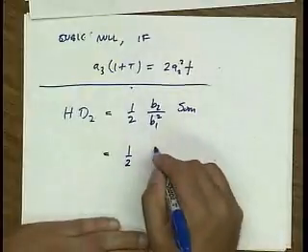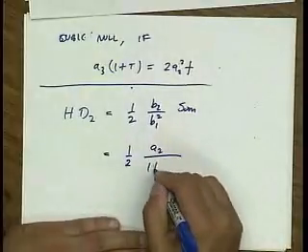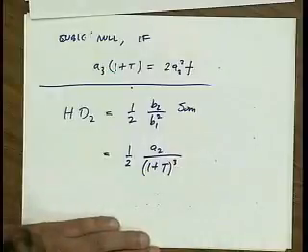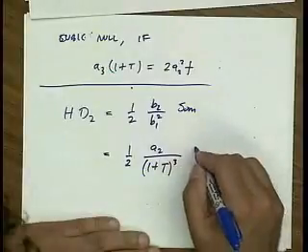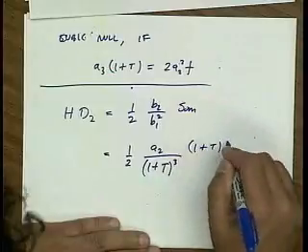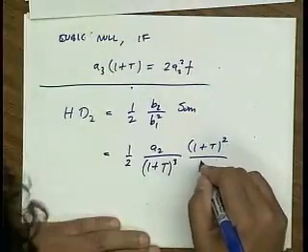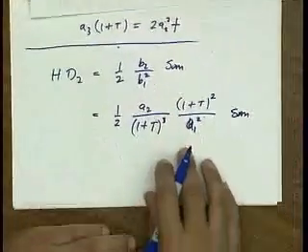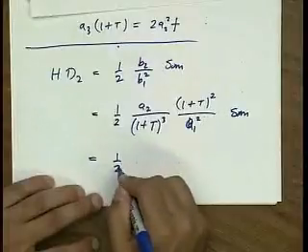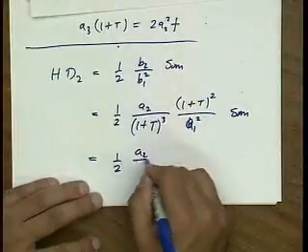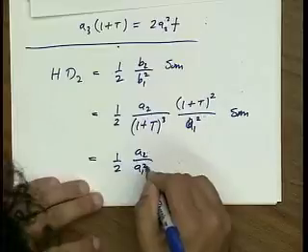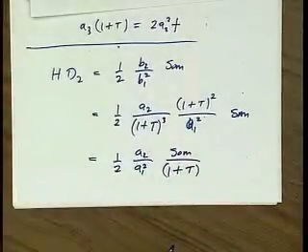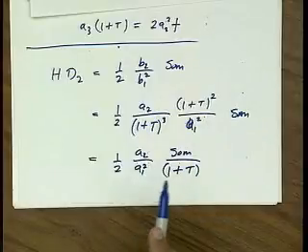So if I substitute, the b2 I found is a2 reduced by the cube of 1 plus t. And b1, of course, is just reduced by 1 plus t. So when all is said and done, the output referred distortion is reduced by 1 plus t. Now why is it very important to look at the output referred?